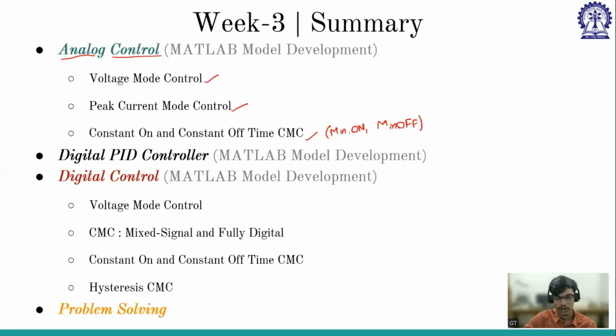All the logics we have discussed. And after that, I have shown the digital PID controller, what the equations of the digital PID controller are, and how to implement it in MATLAB. Then we moved into the digital controller. In the digital controller, I have explained the architectures followed by MATLAB model development. First, I have shown the digital voltage mode control, and in current mode control, we have done the mixed signal, but I didn't get time for fully digital.